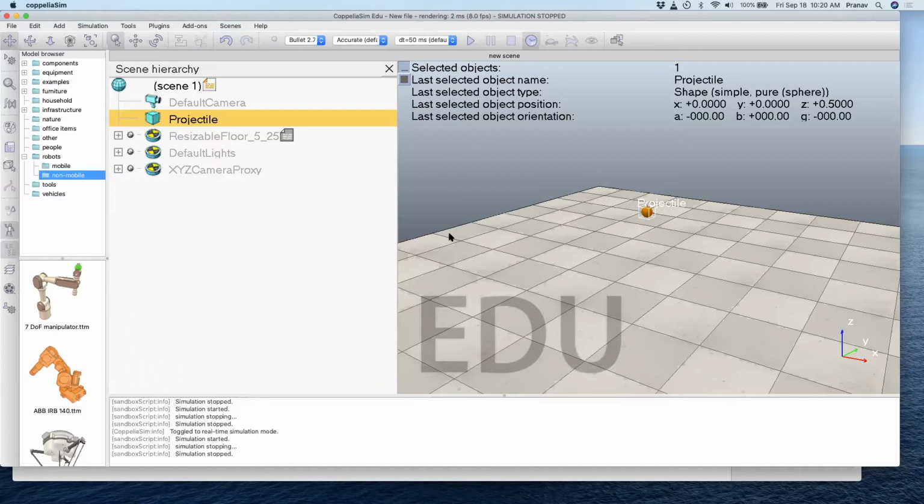Okay, question. What is the difference between parent and world frame? So when you do multiple rigid bodies, like say a 2-link pendulum, then you can specify the coordinates or the position of link 2 with respect to link 1. So in this case, link 1 is the parent frame. We'll see that later on when we do a double pendulum, you'll have actually a parent frame and a world frame. Okay, so hold on to that till later. We don't need it now. In this case, the parent frame is the same as world frame.